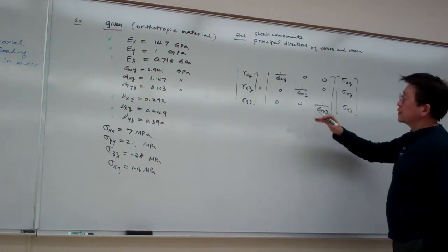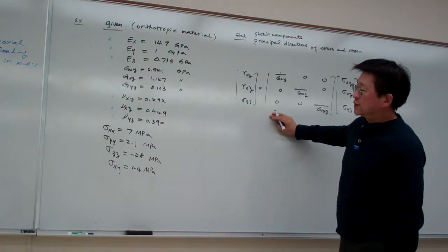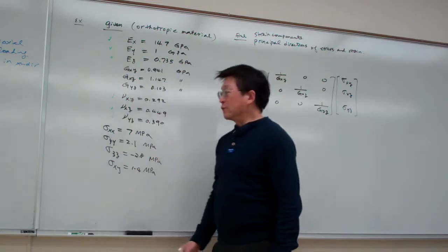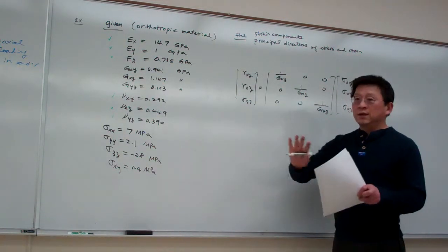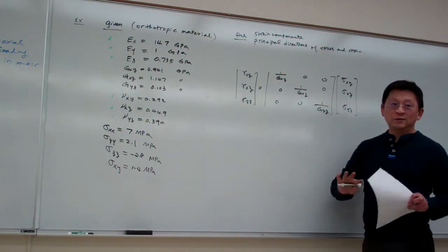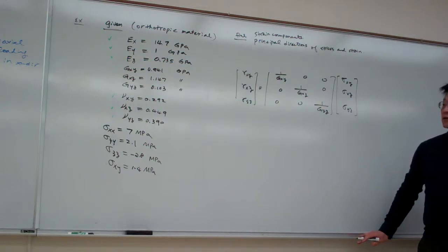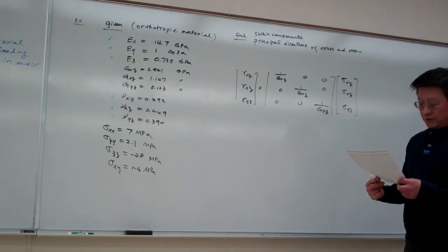Okay, so this portion constitutes the shearing stress-strain relations, and this one is about the normal. And again, for orthotropic materials, the shearing and normal deformations disengage from each other, so we can deal with them separately. Okay. So basically the whole thing we can solve.